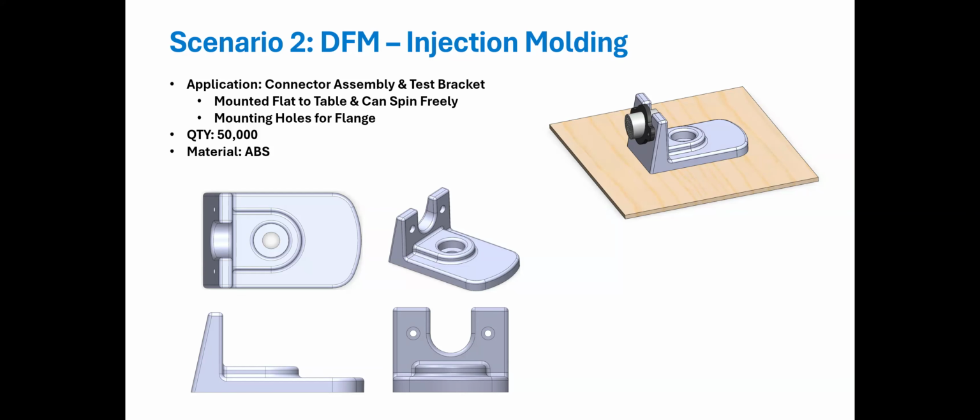As I asked earlier, this design is not designed for injection molding, but my question to you is, what is it missing? Don't worry, I'll go over all of this after. Probably equal wall thicknesses for injection. Correct. So uniform wall thickness